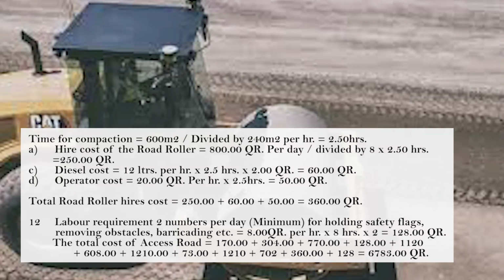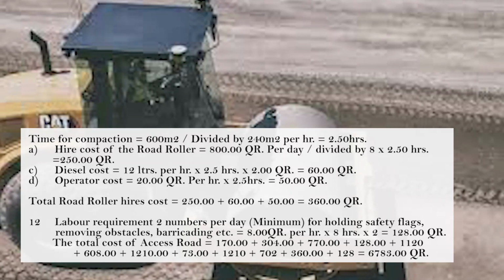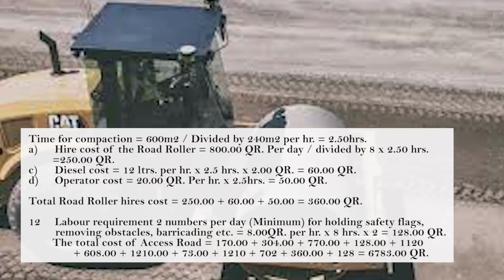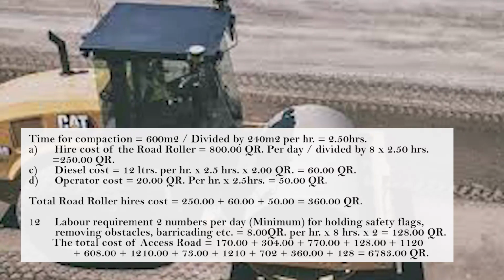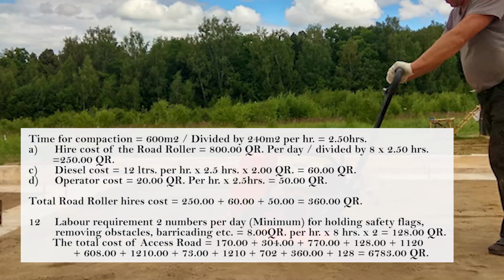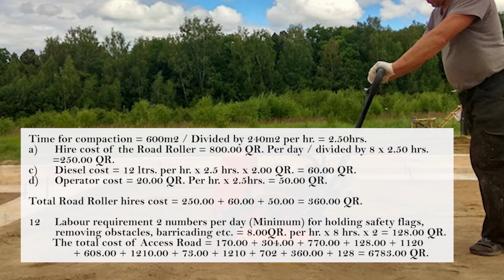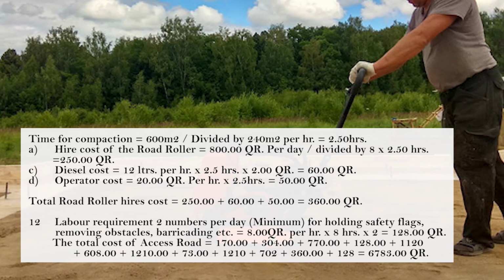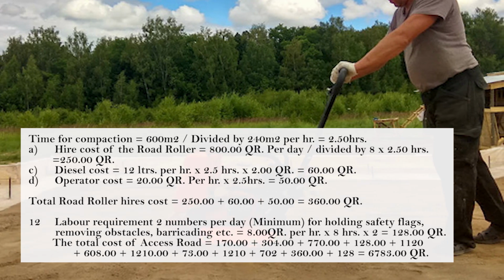Hire cost of the road roller equals 800 Qatar riyal per day divided by 8 multiplied by 2.5 hours equals 250 Qatar riyals. C. Diesel cost equals 12 liters per hour into 2.5 hours into 2 Qatar riyal equals 60 Qatar riyals. D. Operator cost equals 20 Qatar riyal per hour into 2.5 hours equals 50 Qatar riyals. Total road roller hire cost equals 250 plus 60 plus 50 equals 360 Qatar riyal.